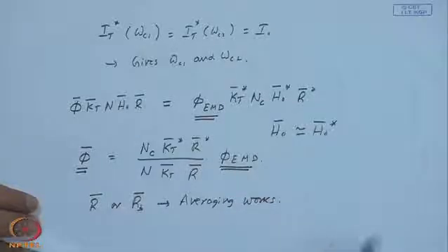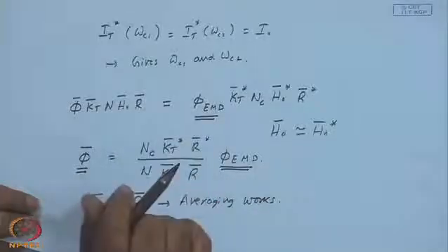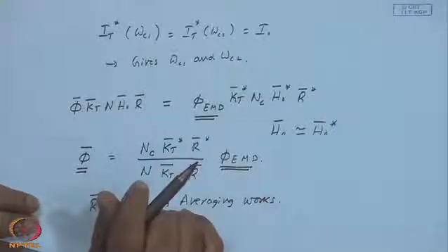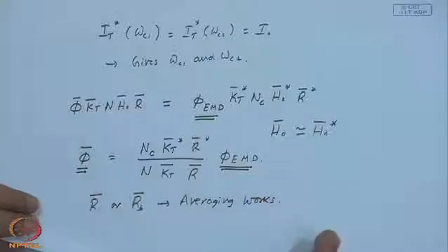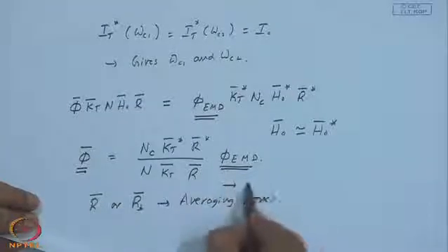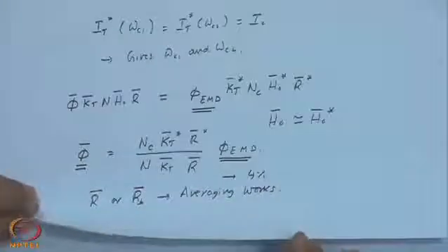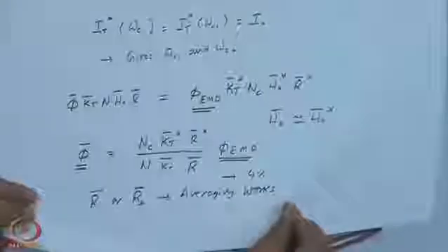Mainly because when you are calculating the tilted solar radiation, each day is contributing. So, taking a clue from that, we have found out the days that contribute to the solar radiation above the critical level and took the average of that, and it predicts almost within 4% of root mean squared error compared to data or any other correlation that you can think of, either the Klein's or Collares-Pereira and Rabl's.